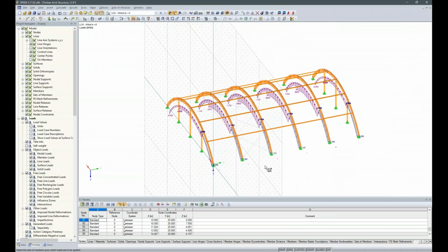Actually, I should add a few more horizontal loads on the gables now, on the gable columns, and horizontal loads on the girders, but that would take about 7 to 10 more minutes, and I don't want to bore you, so I've done that in another file. I'll show you when I'm done with that, and I go ahead and add another load case.